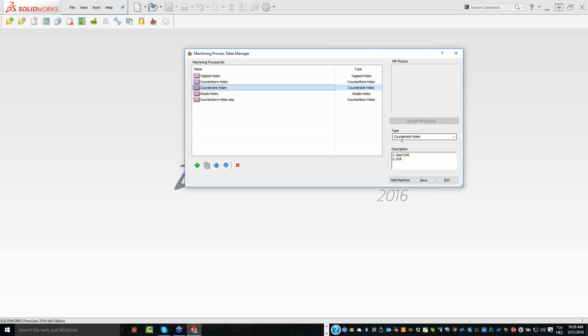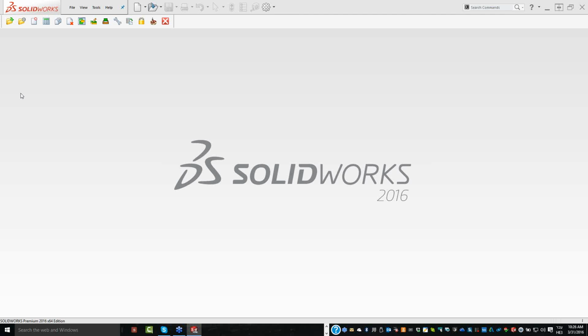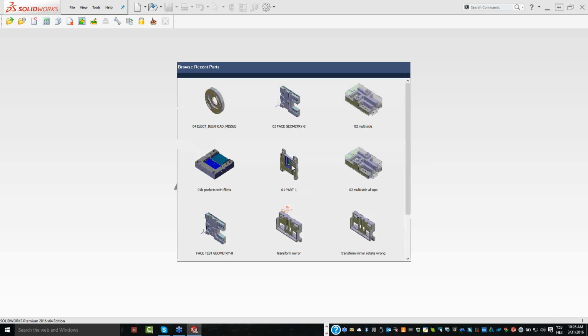Okay, I think I'm basically finished with the webinar itself. Just a little recap of what we showed over here. We showed the depth option inside our pocket operation, pocket recognition. We showed also how to work on fillets, multiple sides, and also working on the advantages of working with pocket recognition instead of pocket on complex faces with many open edges, as shown in this particular part over here.